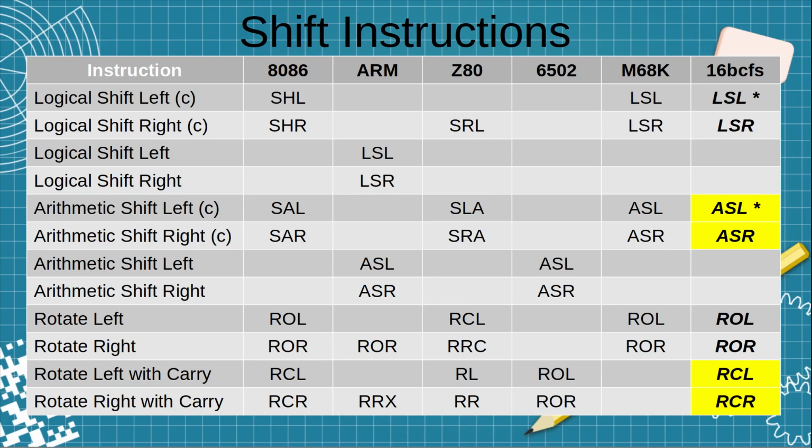And then ultimately the logical shift left, or LSL, and arithmetic shift left, ASL, are really the same instruction. There's no functional difference between them. There's no difference in the result of those instructions. They both shift to the left and zero fill the least significant bit of what's being shifted. The big difference is in the readability of the code, so I'm likely going to implement one of those and then have a second instruction of a different name that performs exactly the same function,